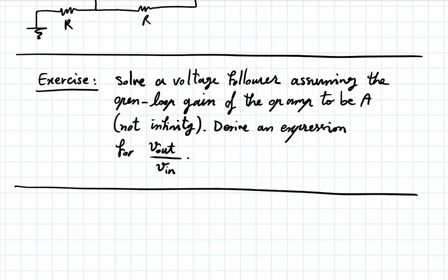If you build a circuit without being aware of that input offset and adjusting for it to eliminate its effect, very likely your circuit will not work in the linear region. Things are normally so sensitive in an op-amp circuit that a small offset at the input that you didn't expect could get amplified and saturate your output.